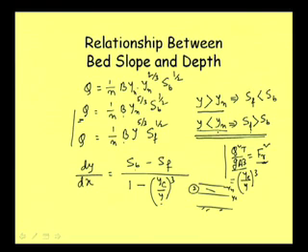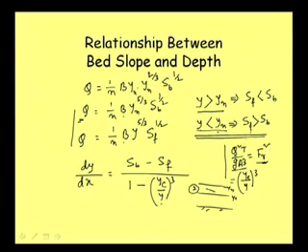So, if SB is positive, as SF is greater than SB, SB minus SF will become negative. And if it is adverse slope, then SB is negative, and SB minus SF, because SF is otherwise also greater, and minus some negative, will always become negative. And if it is horizontal, then also we have the condition that SF is greater than SB.